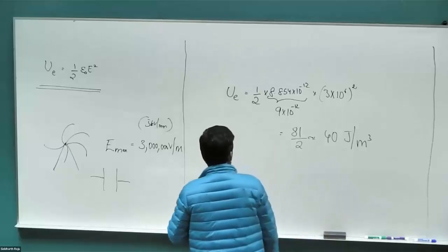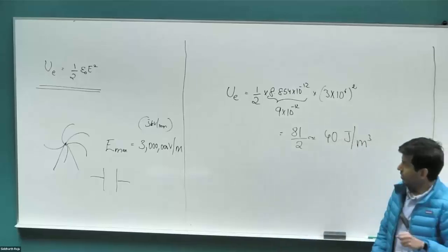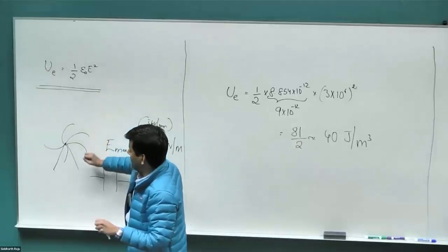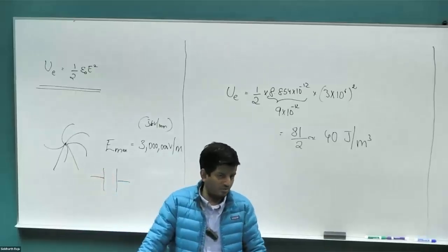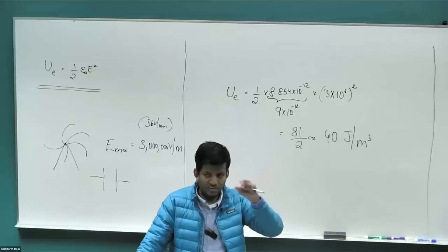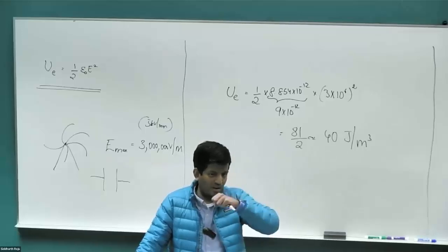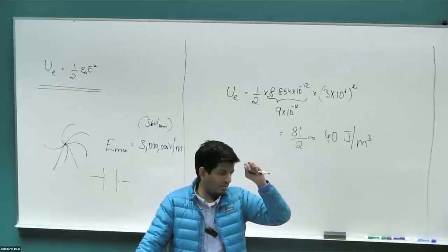Right? So there are two ways we can increase this energy density. One is going to a higher electric field, but that would require changing the medium because air cannot sustain a larger electric field. How many of you have taken a power systems course? All right. So what kind of material is used in the relays when they open the switch gear? There's a special fluid that fills the switch gear so that the discharge does not happen. Typically, when you open a high voltage switch gear, you would see that arcing, and that again is detrimental, and you want to avoid it as much as possible.